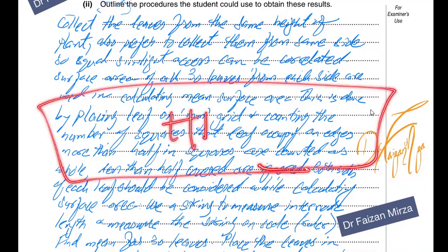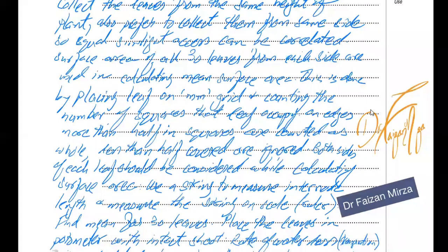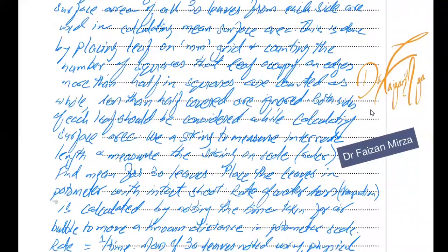You just keep it on a grid, you draw an outline, and you just count the number of squares which it occupies. And on the edges, all the squares that are more than half in, they are counted as a whole square. And any square which is less than half in, you ignore it altogether. Add up all these squares together, that gives you the surface area. Okay, so that's done. Then surface area is calculated. How will you move to the next thing? So calculating the surface area.